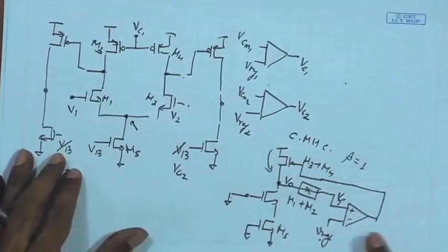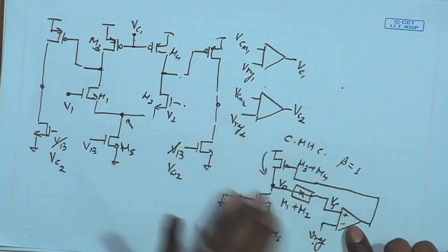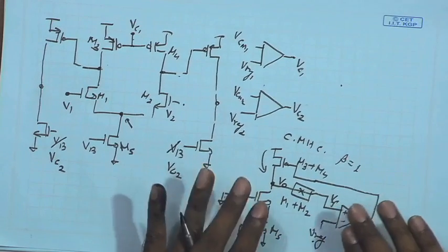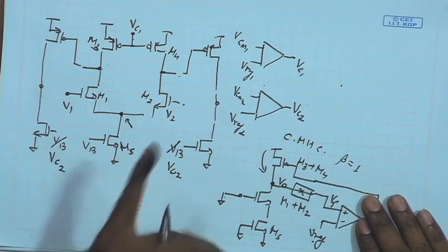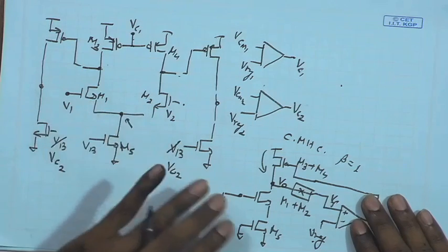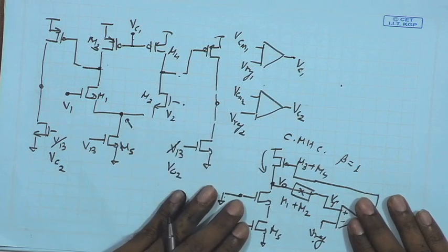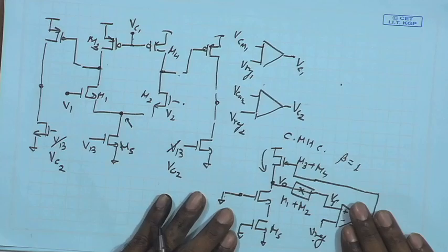So, we can draw the transistor level implementation of this amplifier and then analyze this in the open loop case to obtain the stability, phase margin, etc., using the frequency response, and then look for the stability criteria, where and how to add additional components in terms of capacitors to stabilize this circuit and obtain a reliable phase margin. So, let us look at that in the next module.